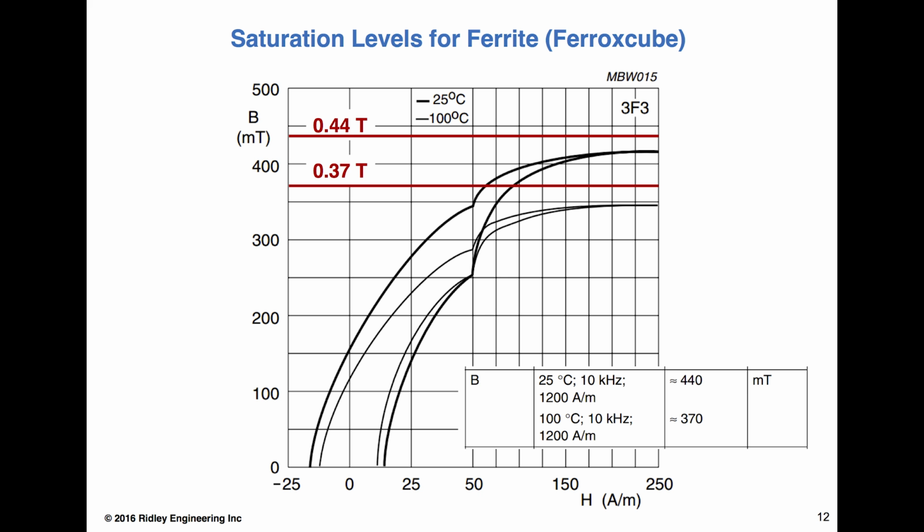So really, there are 2 ways that core loss analysis is going. There's very deep, insightful work trying to find out what all the mechanisms are, and that's nice, and it's good university research to try and understand these things. But when it comes down to it, all we've got is the raw data for measuring these things. It's strictly empirical. And there are many different improved Steinmetz versions, but we're talking about curve fitting in the end.